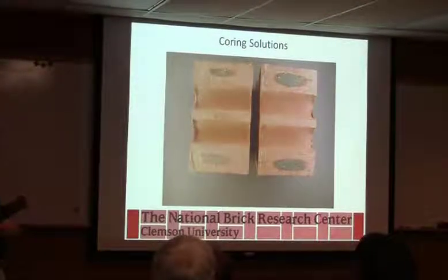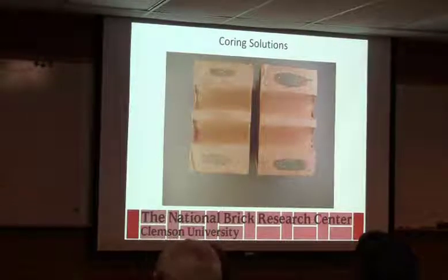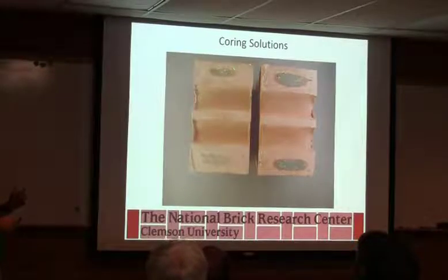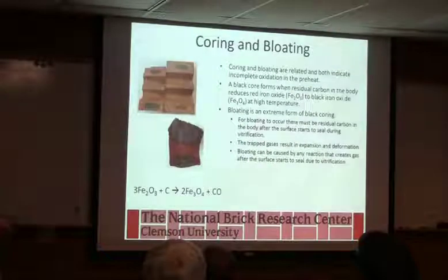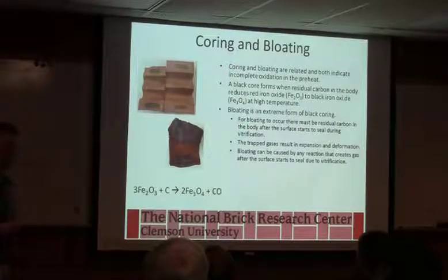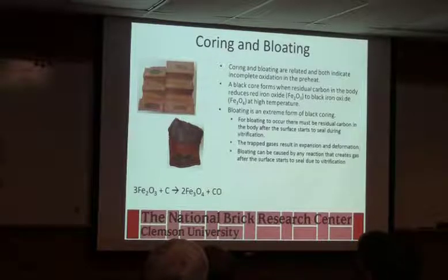This is looking at varying the firing rate to actually show that if you give it time for the oxygen to get in there, you can go through and get rid of the coring. But sometimes you don't have enough time or wiggle room in your schedule to do that.